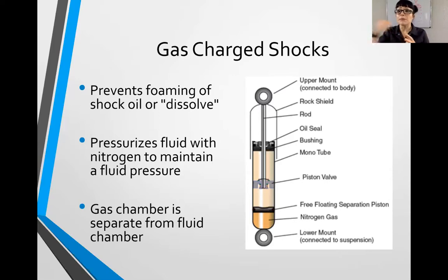And when we get rapid movement, we get cavitation, which is going to help build up air pockets as well. And so pressurizing this fluid pushes either the pockets into the point to where they're so small it doesn't become a problem, or it pushes the air out. So this seal will allow air out. It will not allow fluid out.